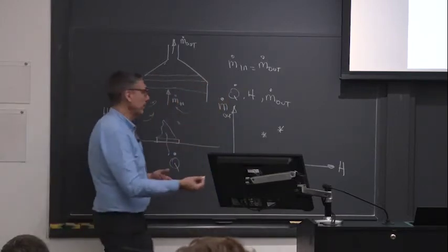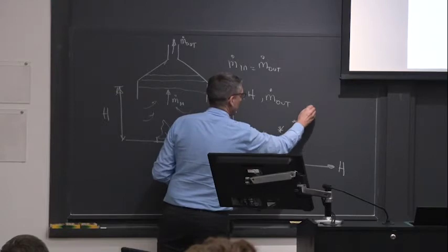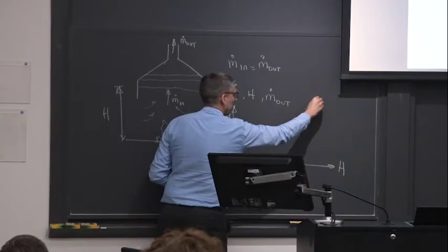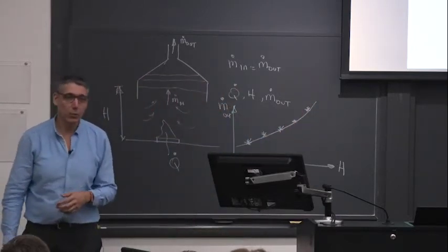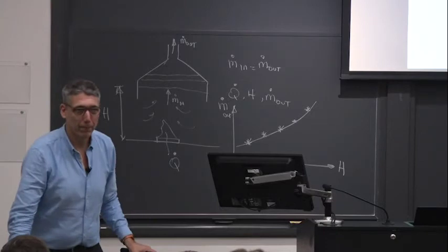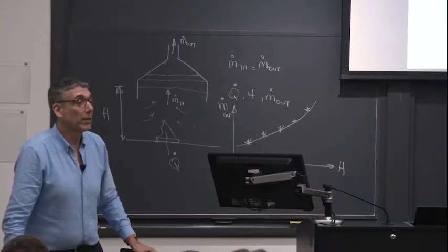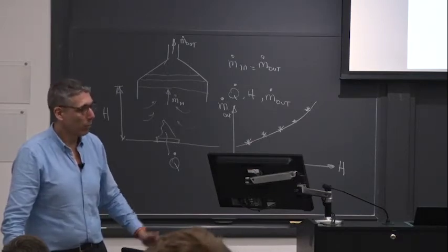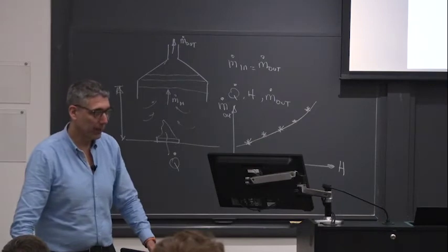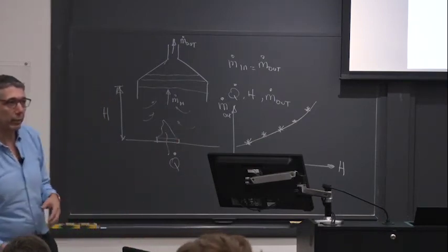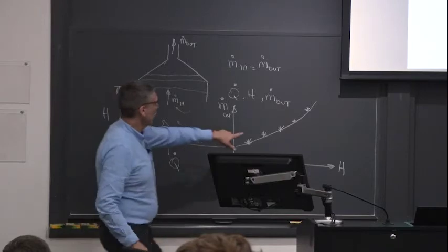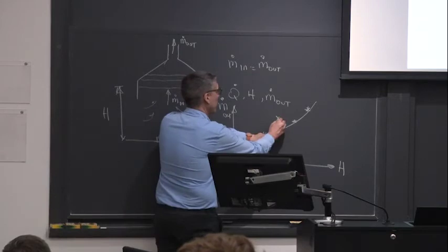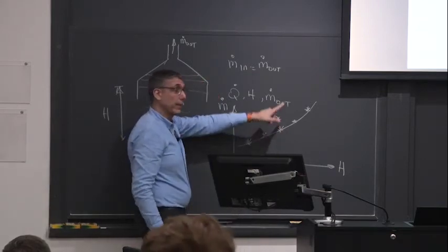Then I'm going to tell him do it again, and again, and now go down. Here's my plot. That is what is called an empirical correlation. Okay? Next, I'm going to say, okay, well, let's repeat the game, but now use a bigger heat release rate. So change the burner, put a bigger burner. Okay? And you start burning with a bigger heat release rate. Now, the same point that originally was here, because it's a bigger heat release rate, it's going to have a bigger entrainment, so it's going to be here. Is that okay? And then I'm going to repeat the whole thing.